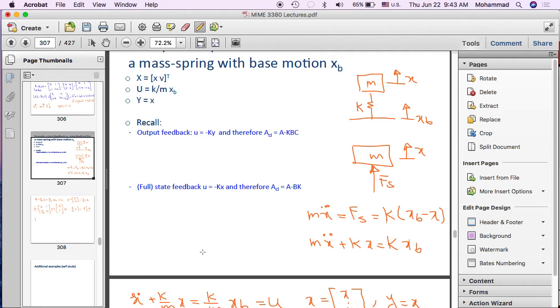It essentially means damping ratio is 0. So damping ratio of 0 means angle to the imaginary axis is 0. So you are on what axis? You're on the imaginary axis. So our prediction is we get two poles that are purely imaginary. Let's see if we get that, or did we do something wrong?